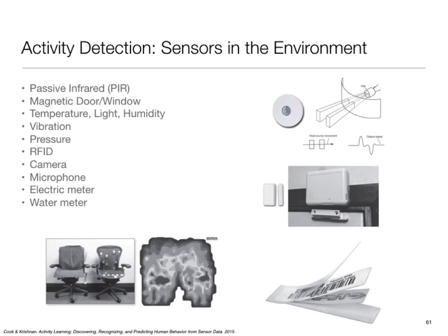When it comes to compressive sampling, since we are sampling at random moments, vanilla chips obviously don't have them. So you are going to arrange somehow that there is a timer tick, but then on that timer tick, you're going to do a lookup at that matrix and say, okay, shall I sample or not, for example. But there are also chips which were designed specifically for this paradigm.